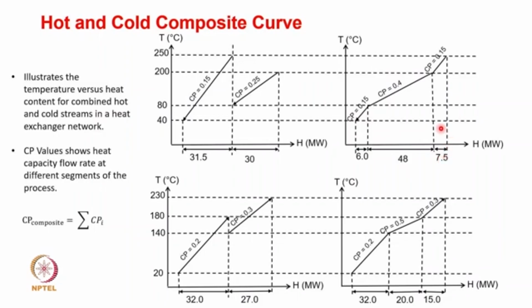How are you getting these numbers? Simply by plotting it. There is no way to analyze further. Once you plot and integrate them together, at the points where they intersect, you drop a perpendicular down and find out the coordinates, and thereby compute the individual heat utilities of these particular streams. In fact, it's not a heat utility, it is the delta H values.